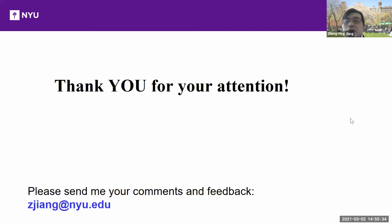So we have two additional questions. What's the maximum number of vehicles in a platoon that can run stably with the learning-based control approach? Okay, again, that's a great question. If you pay attention to the controller design, how many vehicles? As long as we assume that the vehicles can talk to each other within the platoon. Of course, this assumption is very ideal because communication does have a range. If we do allow for centralized communication, then centralized controls are applicable, and the number of vehicles can be large. But of course, nothing is perfect.